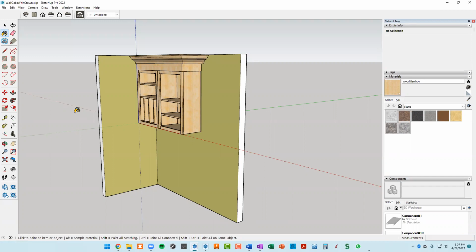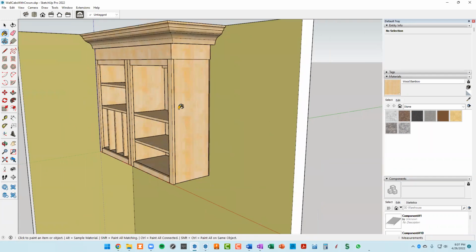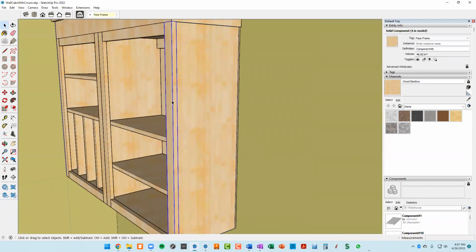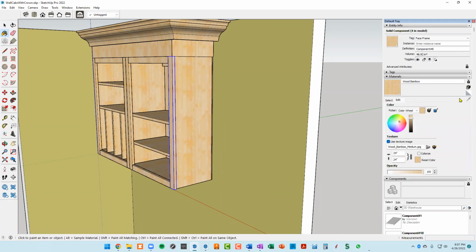And I didn't want to sacrifice the look, you know, like in this case, we got plywood here and we got hardwood here. So one trick around that is if you don't want to set this to different colors or different materials, you could go in to your material and just edit it and make another copy of it so that the texture is the same, but the name would be different.